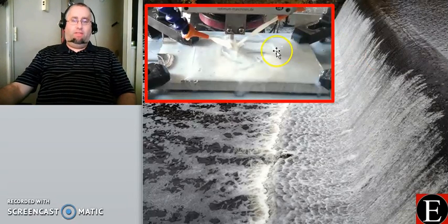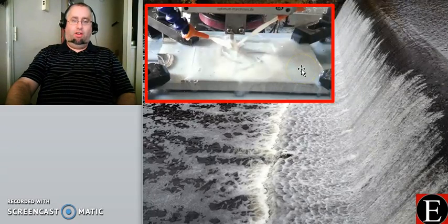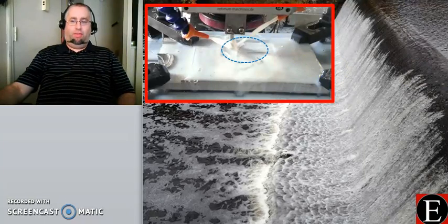And it turns out, if you look here, there actually are two different regions of fluid. This flood cooling is actually creating a hydraulic jump. There's this region of fluid here in the center near the tool that looks very different than this region of fluid out here. I've denoted the boundary between those two fluid regions with this blue dotted line, so you can see the difference there.